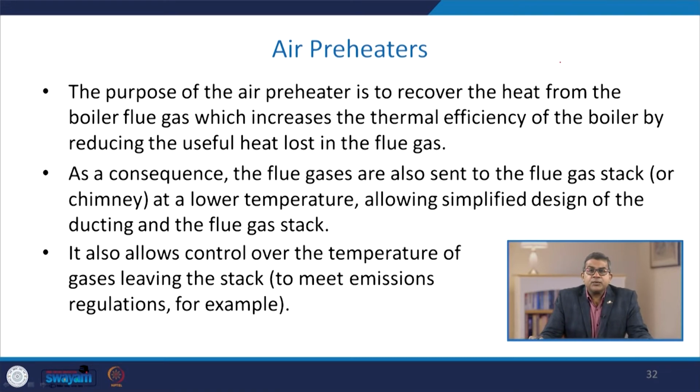As a consequence, the flue gases are also sent to the flue gas stack, for example, the chimney, at a lower temperature, allowing the simplified design of the ducting and the flue gas stack. It also allows control over the temperature of gases leaving the stack. This is to meet the emission regulations, etc.